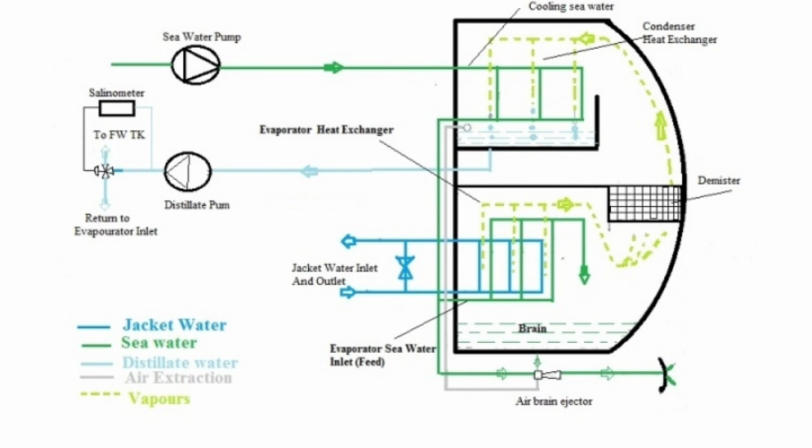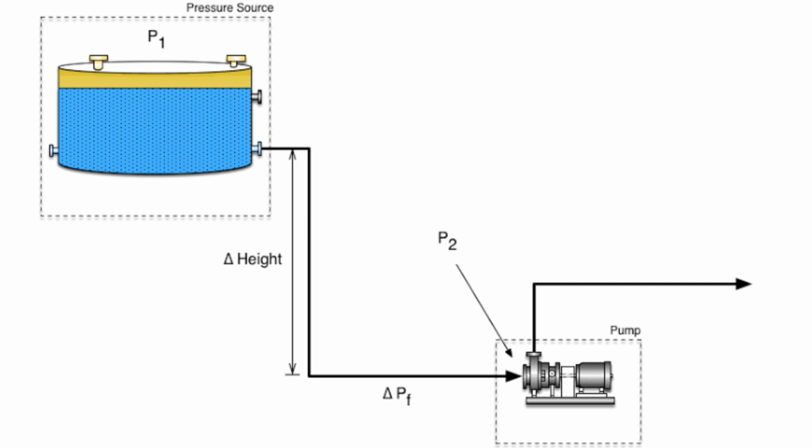In order to get better suction head, distillate pump is placed at lowest possible location in the freshwater generator plant. This is because the freshwater generator shell is at lower pressure. Distillate pump get maximum net positive suction head with the height of liquid column in the suction line.